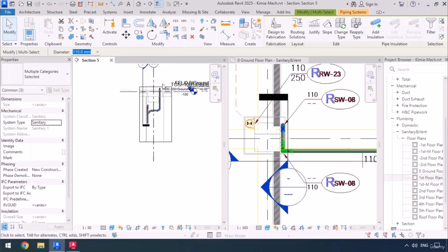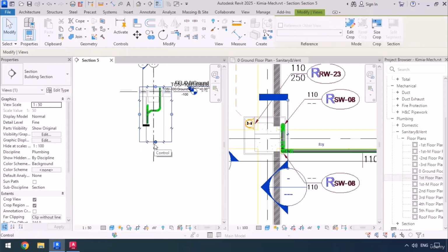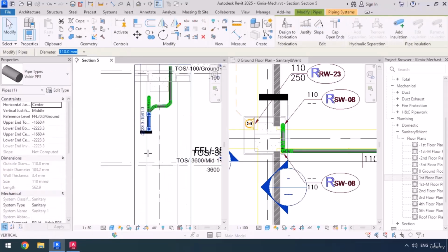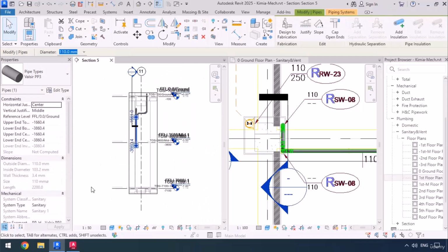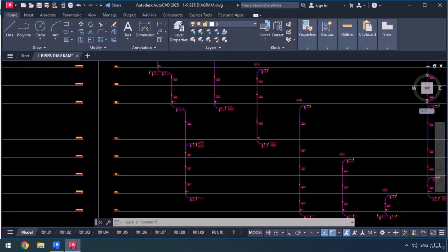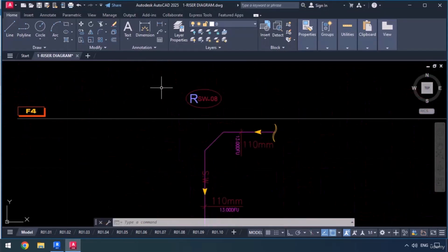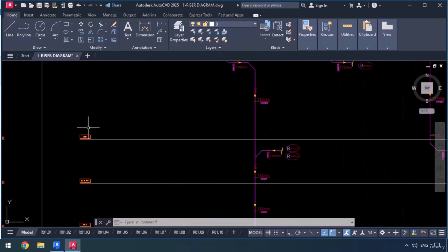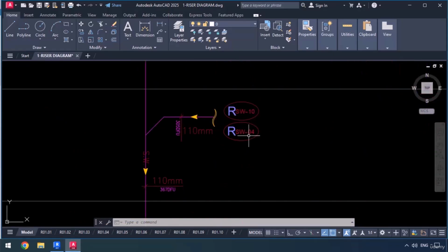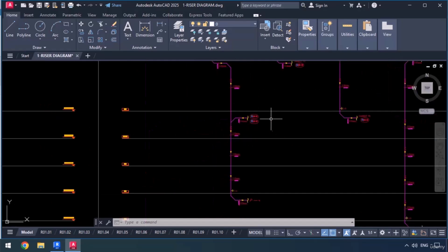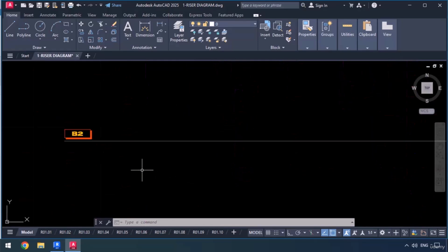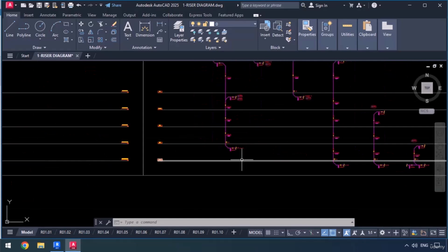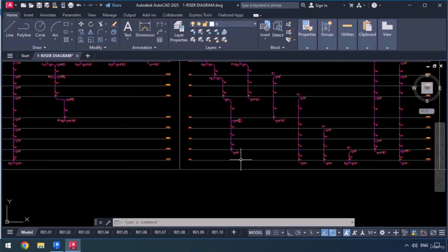Now we're going to check later what's going to be happening to this pipe further up. But for now, we're going to check its path downwards. So I'm going to first go over to the riser diagram, and I'm going to look for and find riser number 8. We were working on the ground floor, where you can see that risers number 4 and 10 are connected to it, and then the riser goes down to the second basement. Then over there in -2 level, it eventually connects to the city sewage.